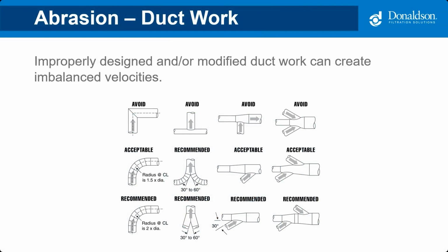And what can happen with a lot of these bad ductwork designs is you're going to wear out those corners on the ductwork, and then you're also going to add a lot of static pressure to the system. And I haven't really talked about that, but static pressure is just the total system pressure, and your fan can only pull so much air.